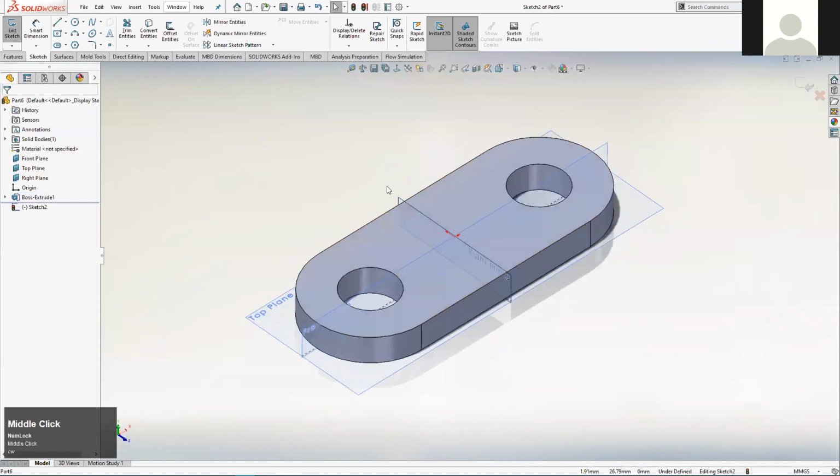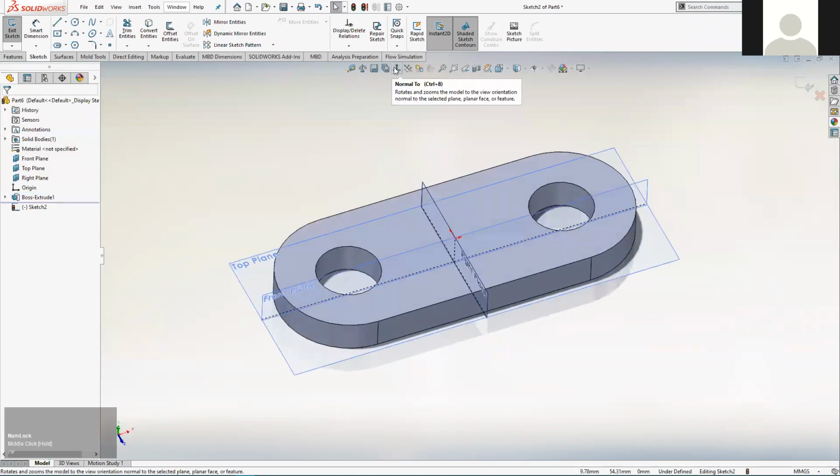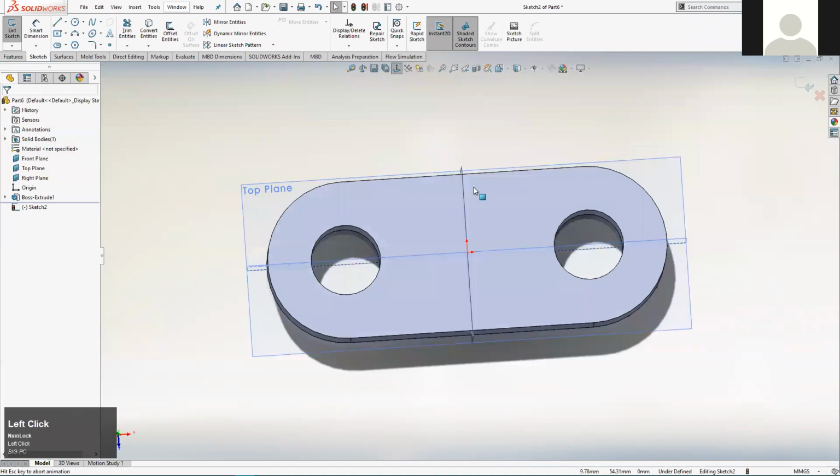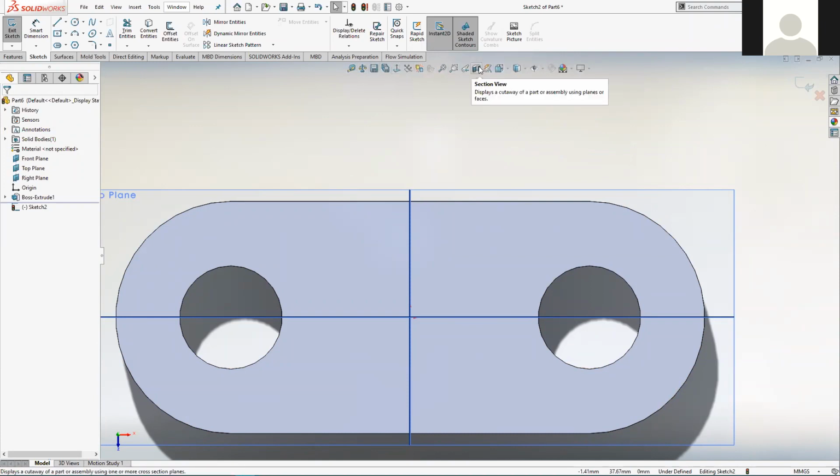I could rotate my view round. In fact, I will rotate my view to be normal to. So normal to. And again, I'm aware maybe some people customize this interface and put that there, but I'll just take a second now to tell you again how to put that normal to icon up there. So if you want any icons available easily on this, I always forget the name, heads up toolbar, I believe it's called. You just right click on any existing icon.